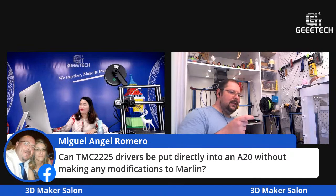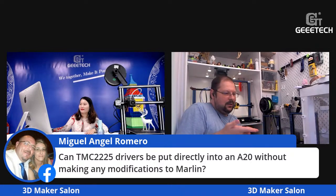That's, I don't know, because I don't know the 2225 driver, but I guess at least you need to change the direction, because the dynamic drivers run the opposite way. So if you change the normal A4988 driver, so the normal drivers, to TMC drivers, you need to change the direction, and that can either be changed in Marlin software, or you can change it by wiring the stepper motor the other way. So the 4 wires which come from the stepper motor, you need to change it and put it the other way, so the motor runs the other direction.